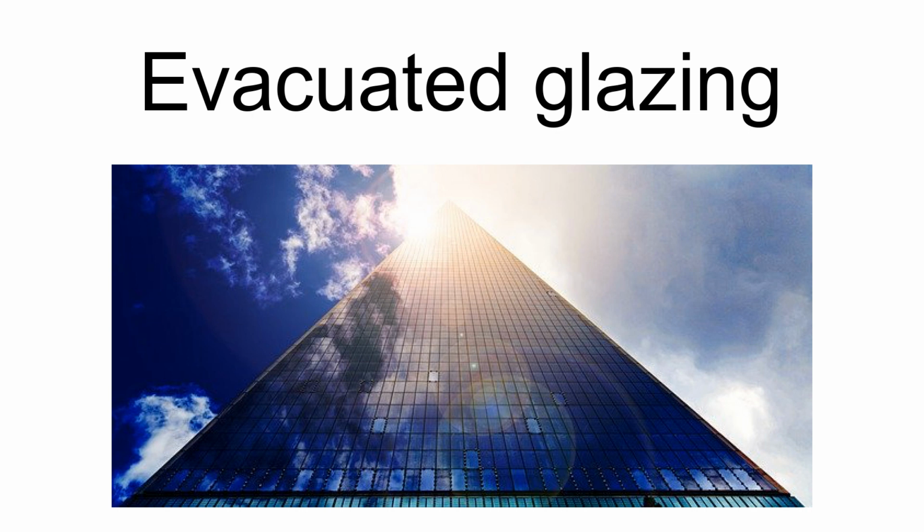Nevertheless, evacuated glazing is still as insulative as much thicker conventional double glazing and tends to be stronger, since the two constituent glass sheets are pressed together by the atmosphere, and hence react practically as one thick sheet to bending forces. Evacuated glazing also offers very good sound insulation in comparison with other popular types of window glazing.